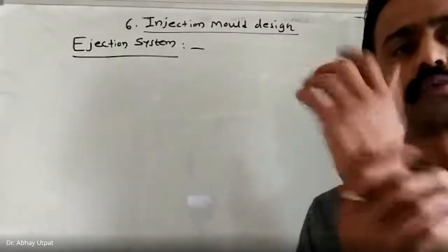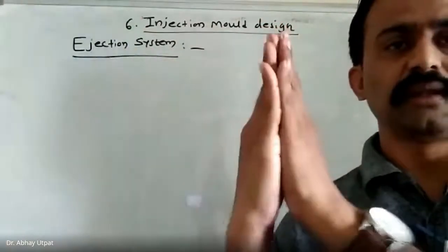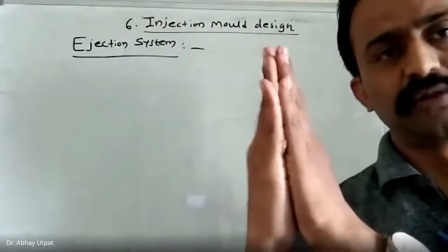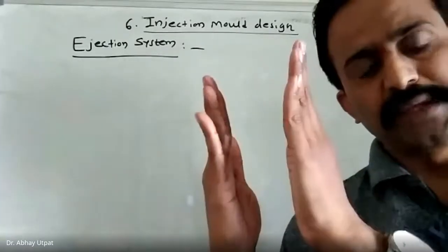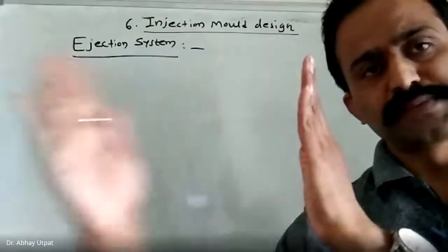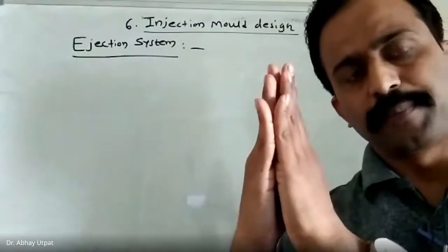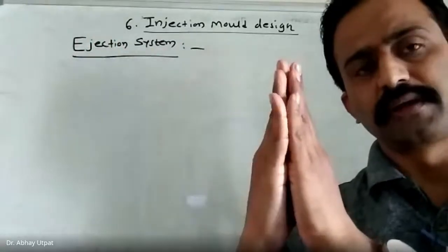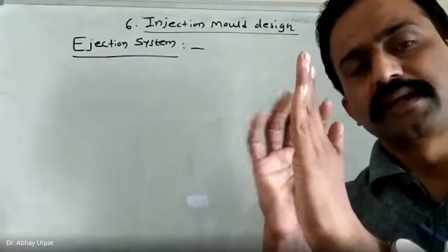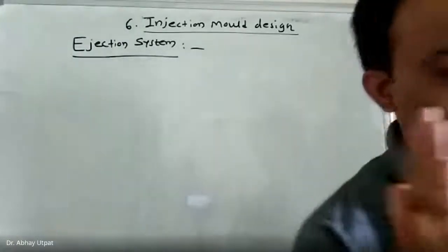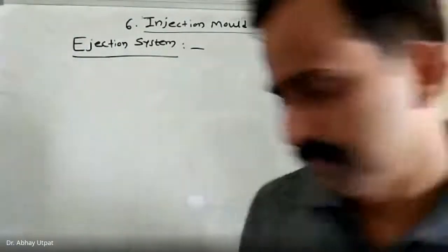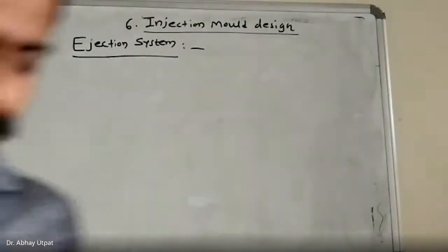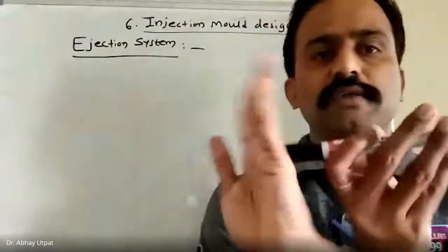Now there are two halves of the mold, if you consider reciprocating horizontal motion. One half is fixed and another half is moving. I repeat, one half of the mold is fixed and another half is moving. The part which is fixed, here is the nozzle arrangement.